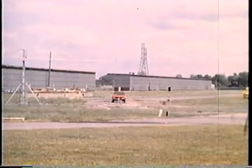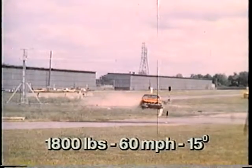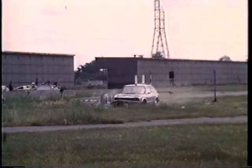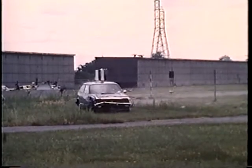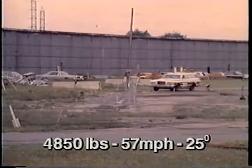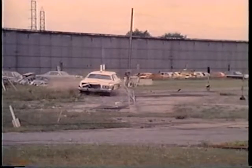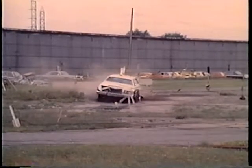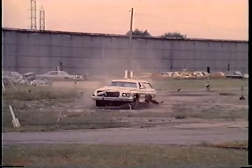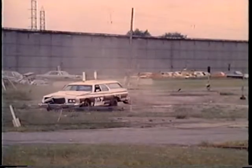In this test series, the small car ran over the anchorage in both directions without being tripped. The performance of the improved anchor was much better than the original design. The improved terminal was also strong enough to provide adequate anchor strength in this large car test. Although these collisions are still severe, this anchor design appears to be the only cable terminal that does not cause small cars to roll over when the impact occurs near the end of the guardrail.